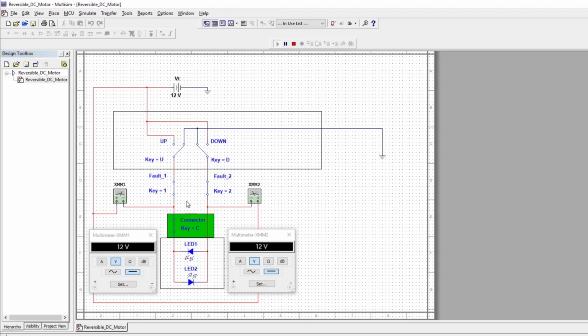So what I suggest is having your voltmeter connected like this, red on the positive, and the negative probing for ground, up the wire through the switch to the common ground here. And when you do that, that's what you'll be checking, this entire run from the motor. And you do the same thing on the other side to check this wiring, and then there again through the common ground. And if it is fine, you'll have 12 volts on both sides.